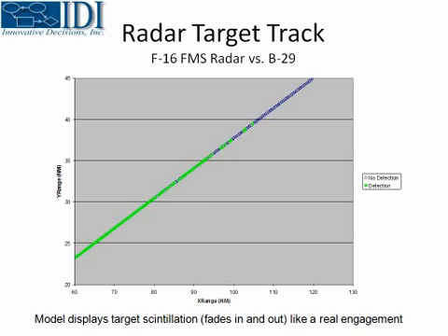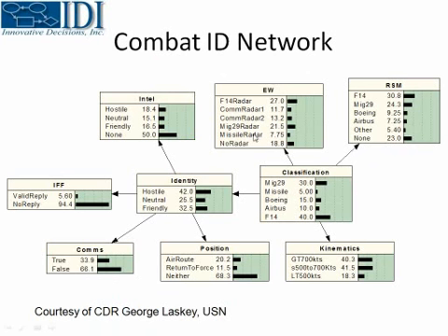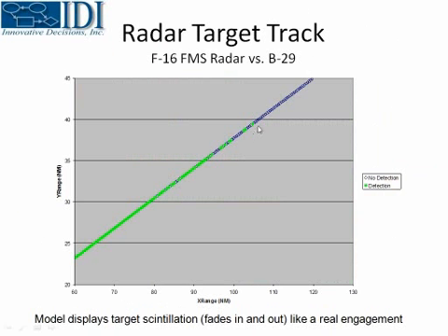Probably most of you have never operated an air-to-air radar, but if you have, this is very much like what you see. You start off at max range where the aircraft is too far away, there's not enough energy, so you won't see it. Then as you get a little closer, particularly when the aspect angle lets you see some of the bigger spikes in the radar cross-section, you'll start to get a few hits.